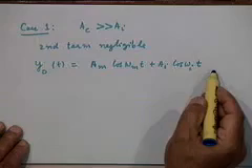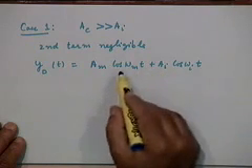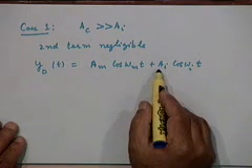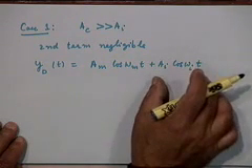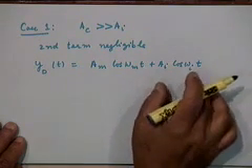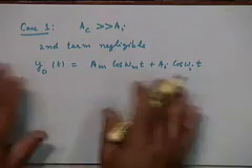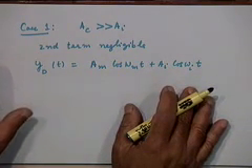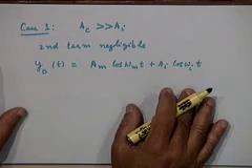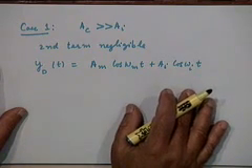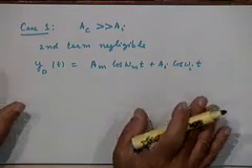It will always produce this output, right? No matter what is the value of AM and AI. If AI is large, of course the output will be large. If AI is small, the output will be small. That's true even here. But for this to work like this, what we are saying is the carrier component must be much greater than the interfering component.